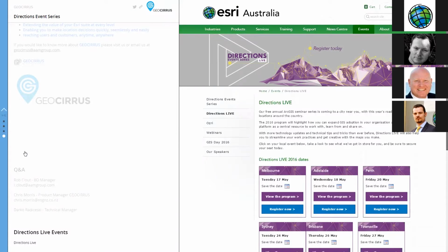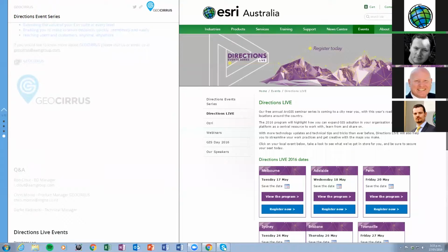So when somebody creates data using procedural rules in CityEngine, essentially that data can then be exported into a geodatabase as a multi-patch, and then that multi-patch will be loaded in Pro, and then, as we showed in the video, can be shared across as a web scene. So the simple answer is, from CityEngine you'll go to multi-patch and you're good to go. Excellent. Cool.